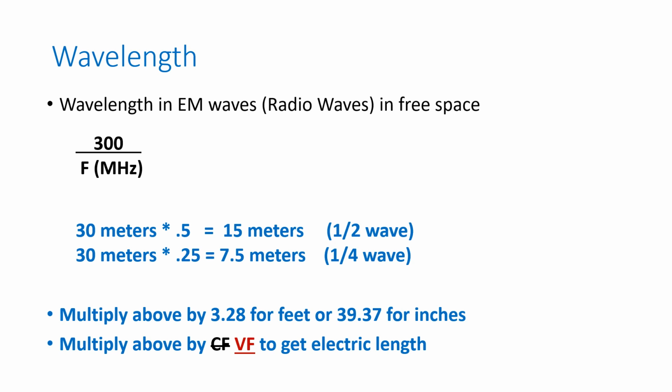So if I multiply times 0.89 and cut my cable, I will have my quarter wave or half wave or whatever length of cable. The reason you would cut cable into certain lengths like that is if you're making a matching harness or you're phasing antennas or something like that. The point is, with coax, it's very easy. You just look up the velocity factor in the spec sheet for the cable. Or, and I'll show you this in a later video, you can use your VNA or other test equipment and measure the velocity factor of coax very accurately with amateur test equipment. Look for that in one of my other videos as well.